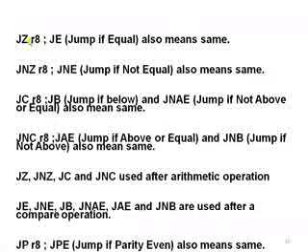Jump if zero and jump if equal mean the same, so both are the same. Jump if non-zero and jump if not equal are again the same. Jump if carry and jump if below are again the same. And jump if no carry, jump if above or equal, and JNB, all these are the same. As you can see, some of these instructions perform a similar kind of operation.